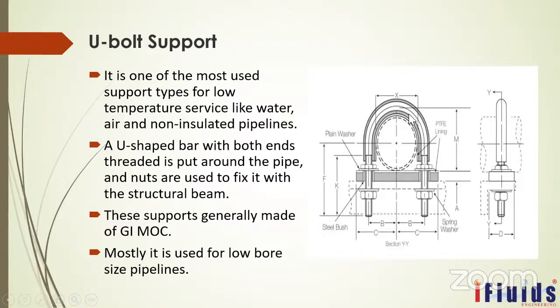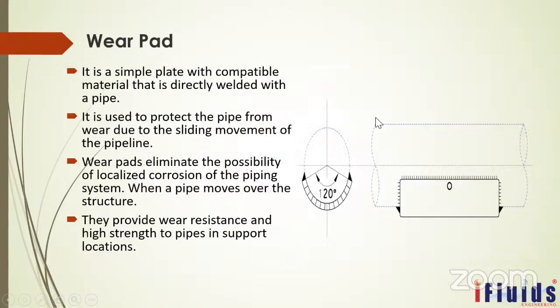If you contact directly to the pipe, there will be some galvanic corrosion. So to prevent that, we will provide the PTFE lining bolt or rubber lining bolt. Based on our requirement, it is available.